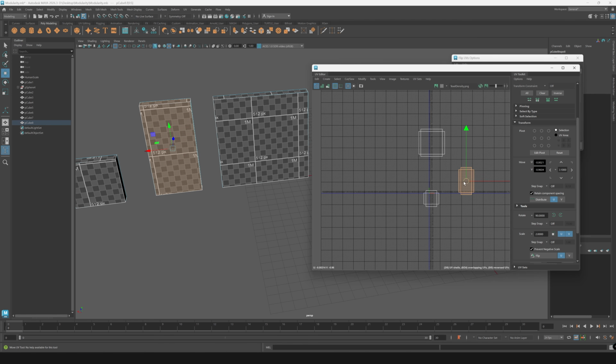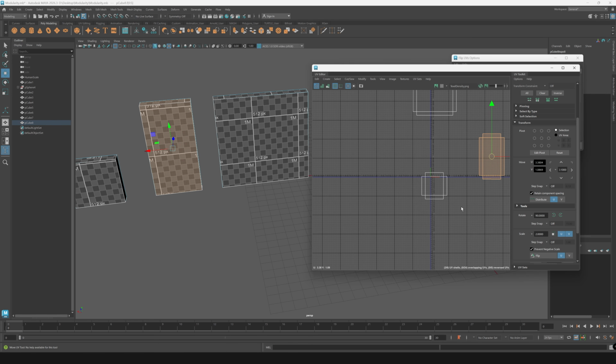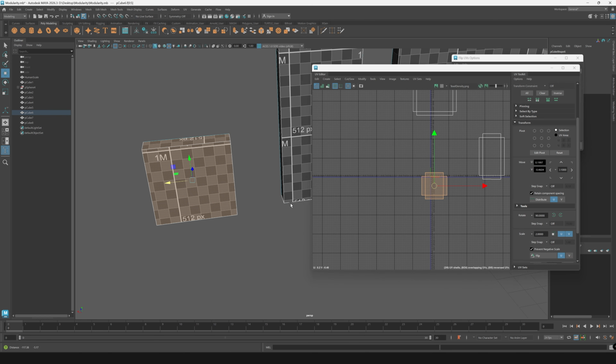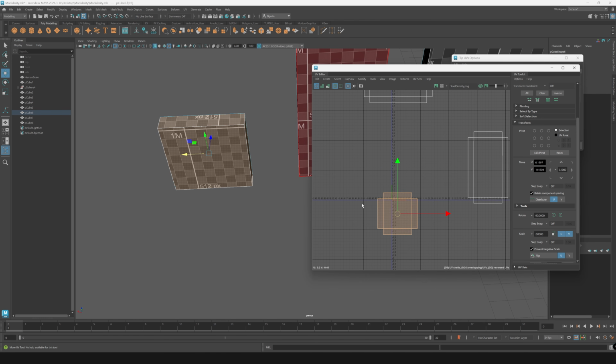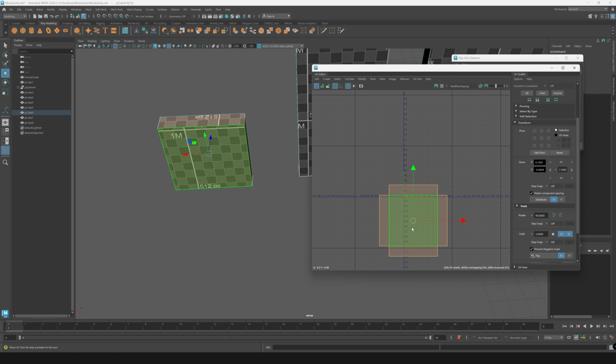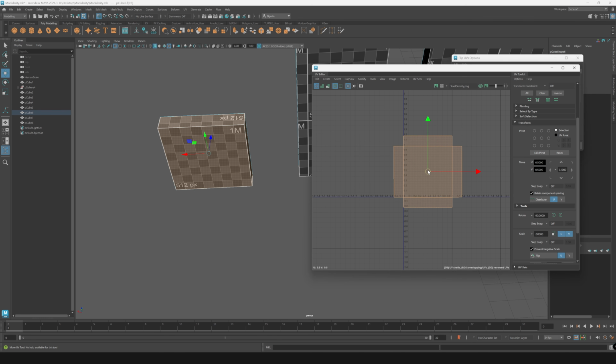So now we effectively have all of our pieces. Let's just make one small change, which is we need to make sure that the edges of these guys all end at a texture UV tile border. Because if not, we're going to have a problem with keeping this thing seamless. So for this guy, very easy, because again, this square shape is actually 1 full meter on both dimensions. So if you just hold X, we'll just snap him right here in the middle. And guess what? End to end, perfect.